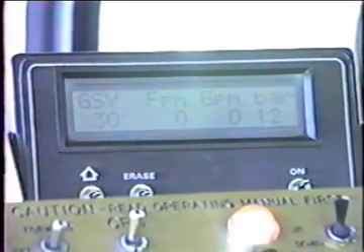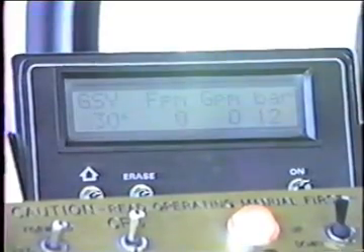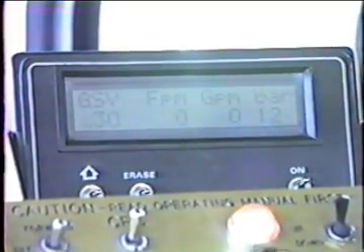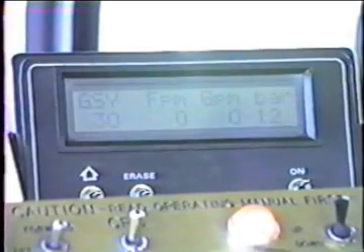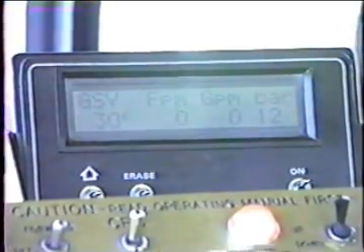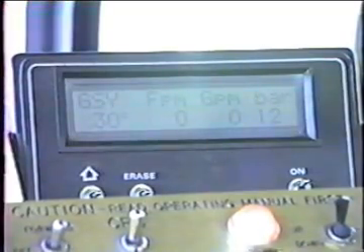It can't see the spray bar, it doesn't know anything that's going on back there, it just sees what switches are on. Just a note of caution there, if we had a wing up, let's say that we had the right wing up, the right wing won't spray when it's up because of the mercury switches that we looked at on the back of the truck. It won't spray at all, but if we had those right wing switches all turned on, the computer thinks that the right wing is going to spray.